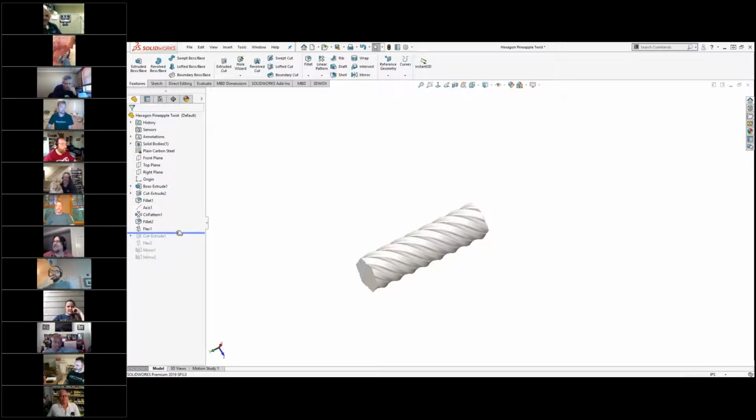Then you take that chisel again and once again cut longitudinal grooves. You also take your hammer and pound the ridges flat before you do that. Then you heat it up one more time and twist it back the other direction. Nice. The diamonds just pop right out.